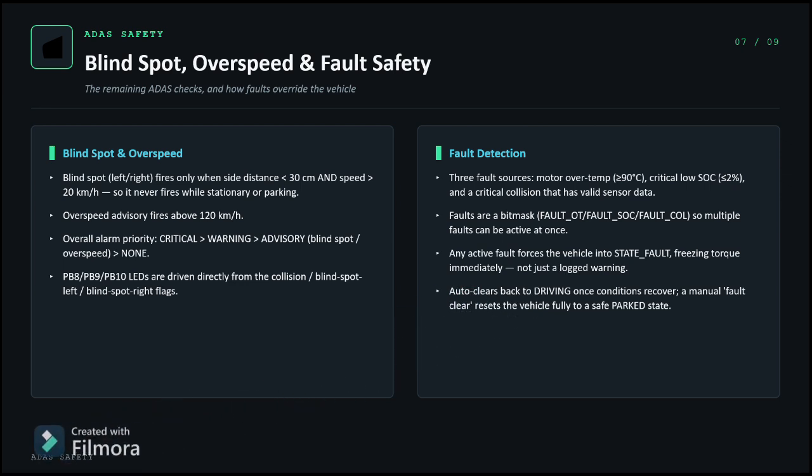Any active fault forces the vehicle into the fault state, freezing torque immediately, not just logging a warning. It auto-clears back to driving once conditions are recovered. A manual fault clear resets the vehicle fully to the parked state.